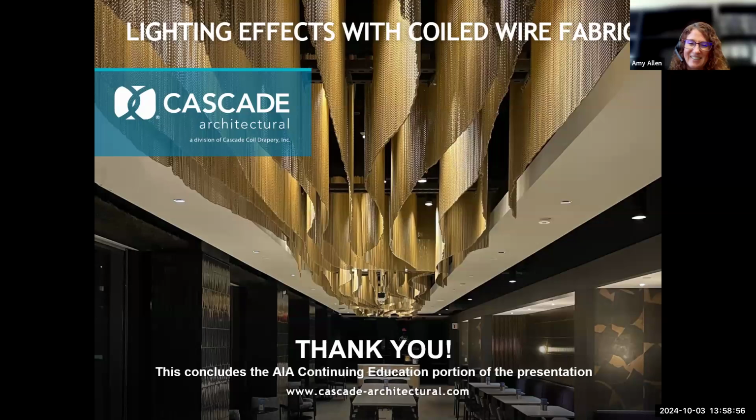So basically you want to pick the right material for that. We would encourage you to go with a 316 stainless steel. Depending on the environment, stainless steel is stainless, it's not stain proof. So the right maintenance would have to be applied to that as well. We would look at all those connections to make sure that they were also stainless. But again, you would have to have the right maintenance program for that system.